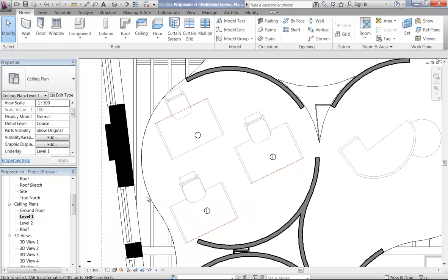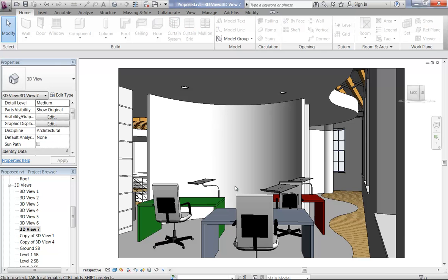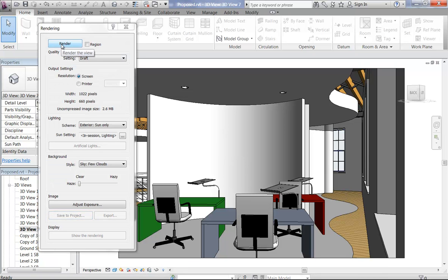Okay, so I'm going to look at that back in the perspective view. And you can see there are my lights, so they're coming up fairly clearly. Now, if I go to render that, it should show you reasonably. So in the scheme there, I'm just going to set it to interior artificial only. And then the quality, I'm going to improve that to low, but everything else I'll leave on default. So now when I render...